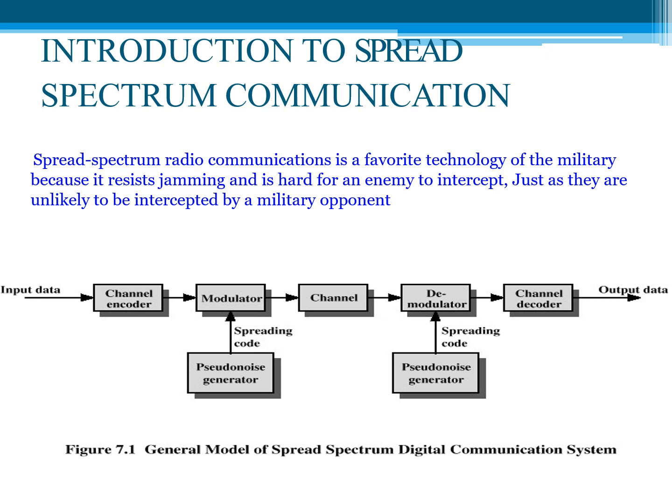Next, the channel decoder at the receiver gets the binary information sequence back. Thus, the receiver can detect the transmitted spread spectrum signal only if it knows the pseudo-random sequence. For any arbitrary receiver, it is difficult to know the pseudo-random sequence since it appears like noise. So, this is the general model of a spread spectrum digital communication system.